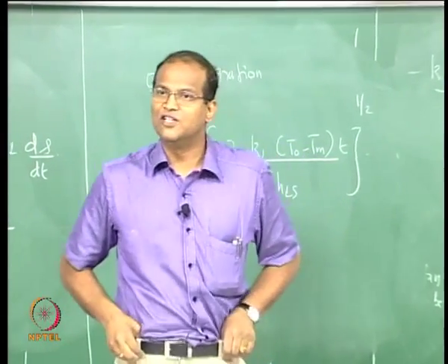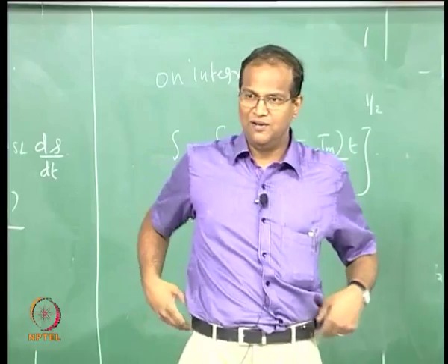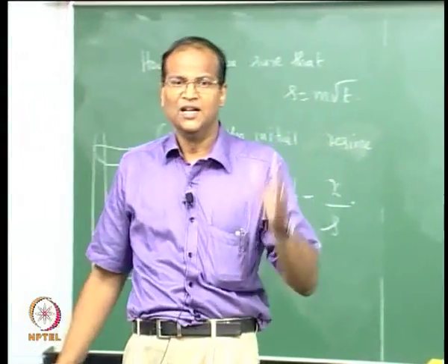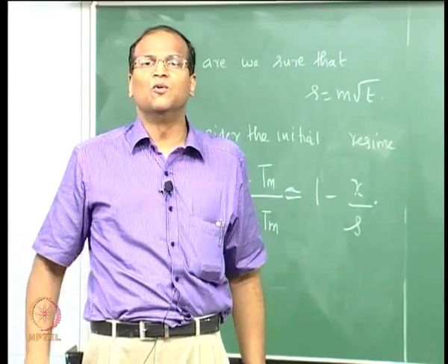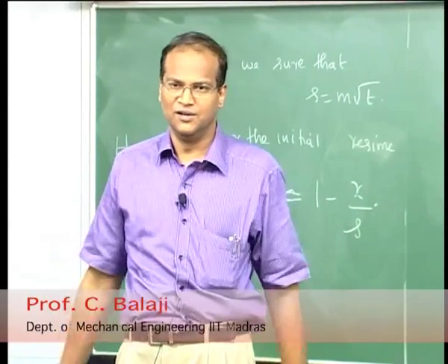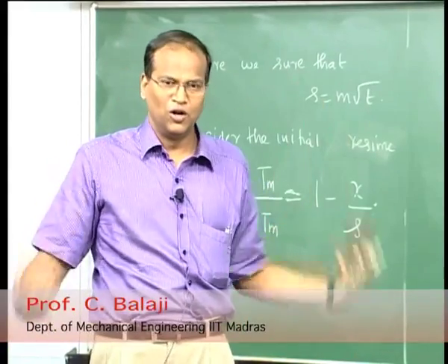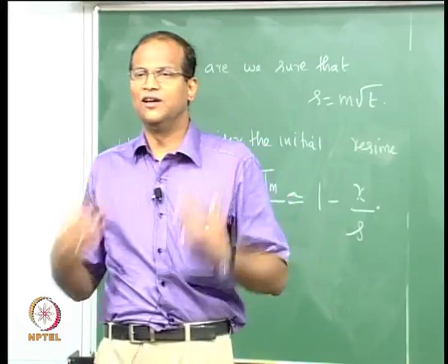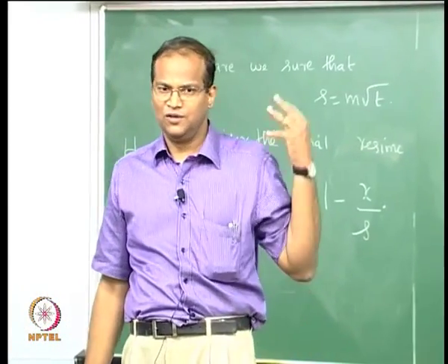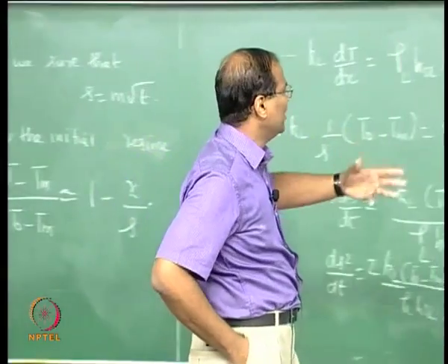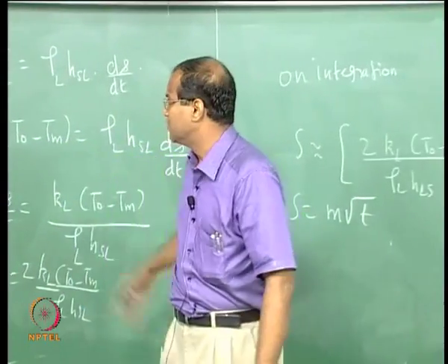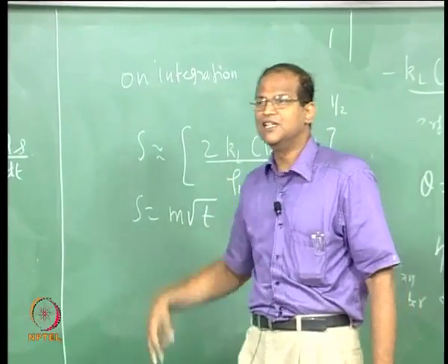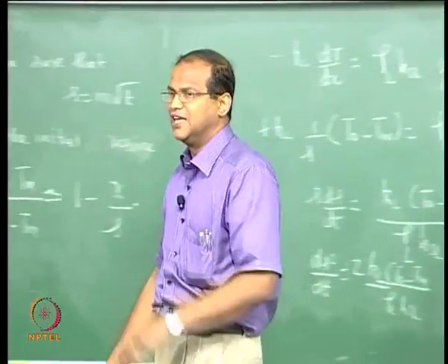So s will be a function of x and y apart from time. S itself is a function of time, that is one thing, and the melt front will also be 2-dimensional. So once you want to model those cases, you want to consider subcooling, superheating, mushy zone and all that, the analytical solutions will break down. You have to take recourse to numerical methods. You can write your code, and the most important thing is the capturing of this melt front. That is why we spend considerable effort now to get S. Capturing this melt front as a function of time is a key engineering result.